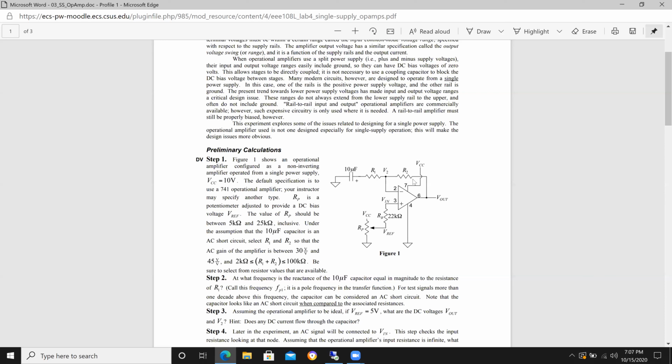So this would be a perfect amplifier for that, to where you could set the voltage that you want the output at, and even better, you can tune it, right? So if you want this output to be a little bit higher, the DC value, or a little bit lower, you could tune it with this pot. Then you're getting the gain within the band frequencies that you want, and you don't care about anything that's happening at DC.